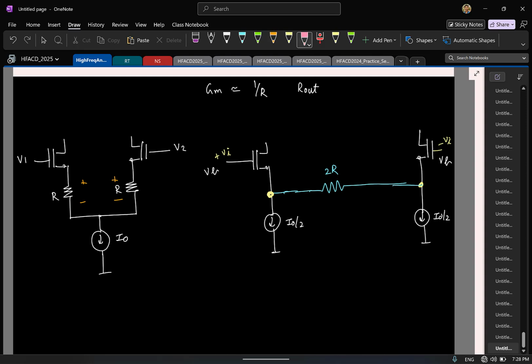So let us say now you look at the left side circuit. If this current source injects a noise current, which it will, what can you say about the noise current getting split in the two sides? They will be identical because both halves are symmetrical. So if I take the output difference, what can you say? That should get cancelled, right? I mean, this is something we saw in a fully differential circuit. Any common mode disturbance sort of gets rejected. So this adds no noise. So I will say no noise from current source.